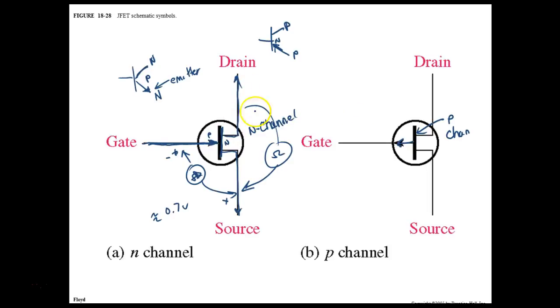So if I put an ohm meter across my drain and the source, I should get a resistance reading. And if I swap them around, I should get the same reading. If I reverse bias the gate to source or the gate to drain, it's going to read like a reverse bias P junction, whatever your meter reads. Most of your meters show OL for overload.